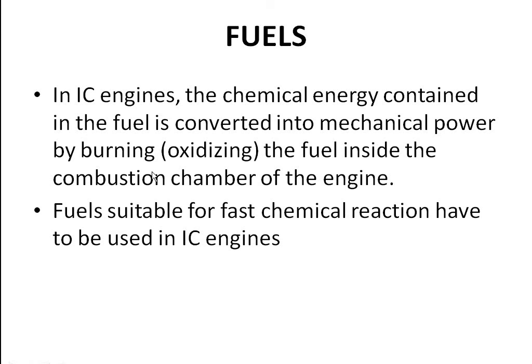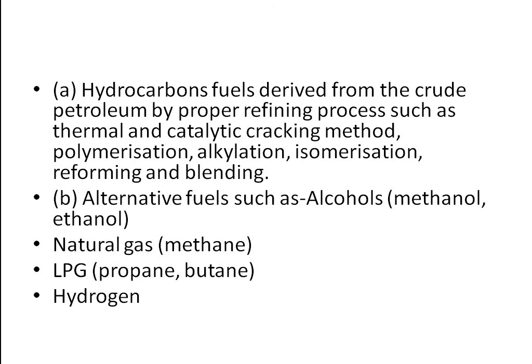Next is fuels. In IC engines, the chemical energy contained in the fuel is converted into mechanical power by burning the fuel inside the combustion chamber of the engine. Fuels suitable for fast chemical reaction have to be used in IC engines. They are mainly hydrocarbon fuels derived from crude petroleum by proper refining processes such as thermal and catalytic cracking methods, polymerization, and different set methods.